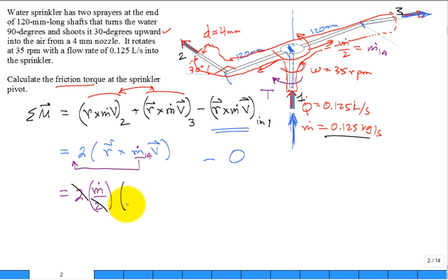We have R cross V. Well, we're going to come out from this axis, true? And we want it to be spinning around this axis as shown. If it comes out the end at velocity v, it'll have an upward component and a sideways component related to that angle of 30 degrees. The upward component will be v out times sine of 30. The other one will be v times the cosine of 30 degrees. Which of the two? The upward makes it want to spin around the axis, or the sideways makes it spin around the axis? The sideways. It's the v times cosine of 30.